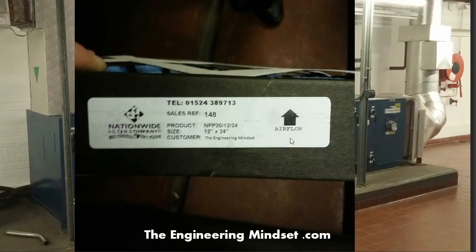But more importantly, you've got the direction of airflow, so you know how to install that within the AHU, how to slide that in so that the air will be passing through this way and out off into the supply duct. It's important to get that round the right way. And just to show you a filter here, this is obviously a new one. Just show you the thickness of these and the materials they use, so you can see straight through it. The light passes through. It's very thin. It changes in density, but yeah, it's very thin material. The thicker the material, the more you will capture, but then the higher your fans will have to work, so the more you spend in electricity.